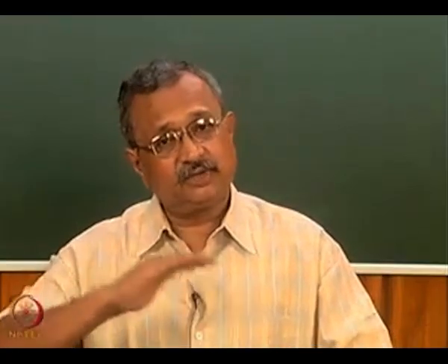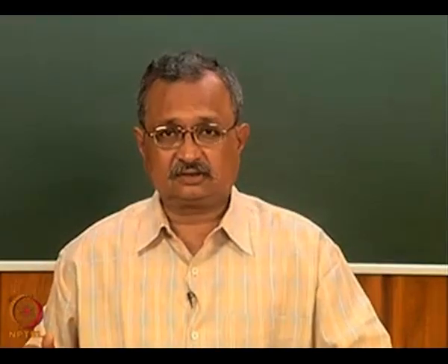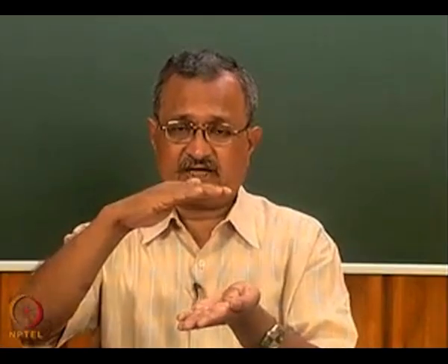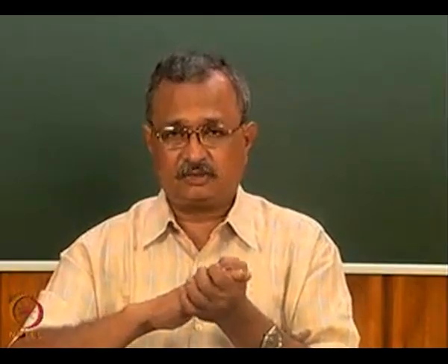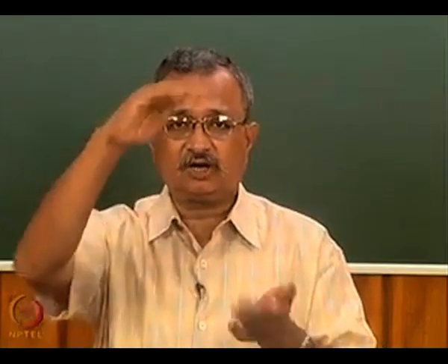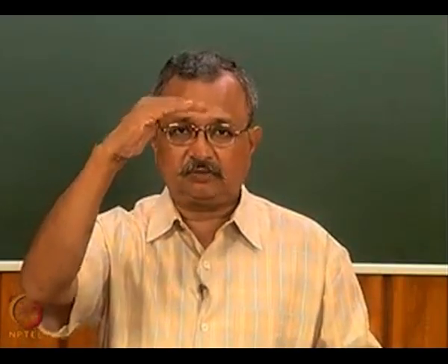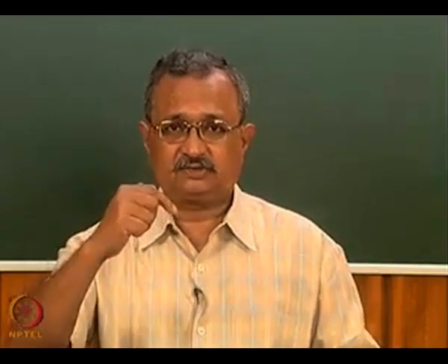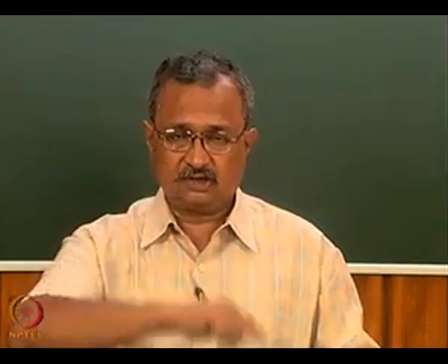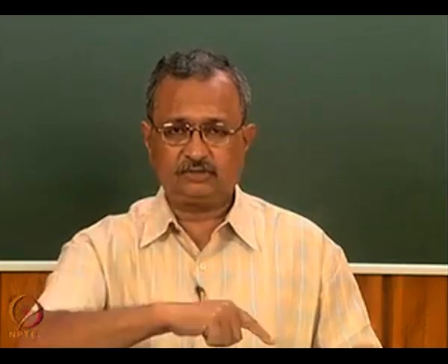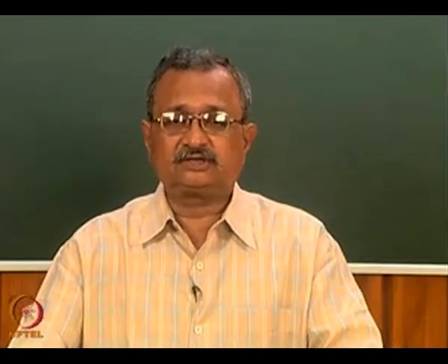In that case, various considerations are to be taken, and the stair height should be below 1/3 of the lower leg limit, meaning from the foot to the popliteal height, that is the back side of the knee, that point. If we take that length, then it will be around 1/3 of that. Then we can say that while climbing, it will remain within the physiological tolerance limit.